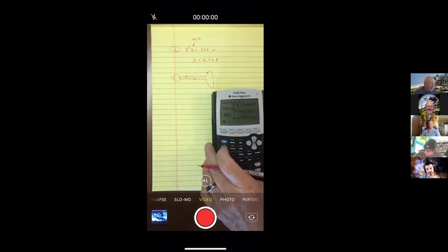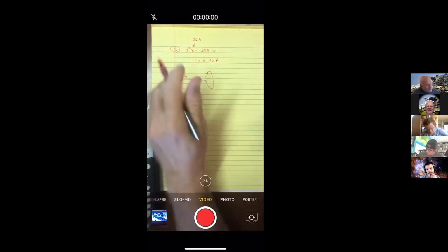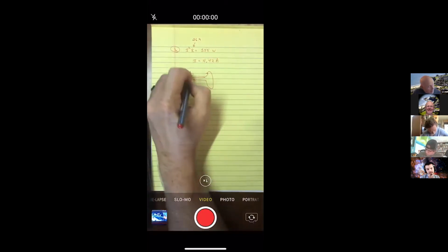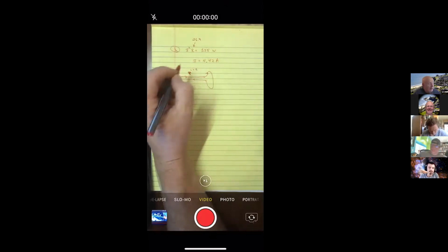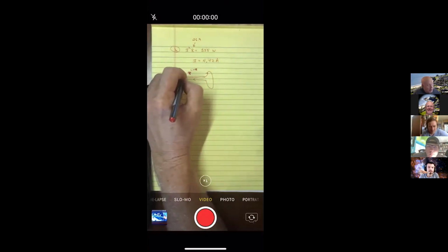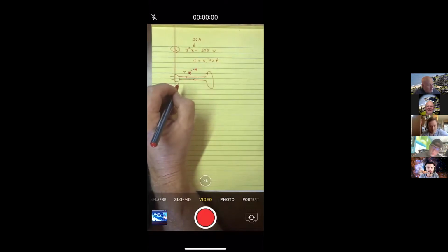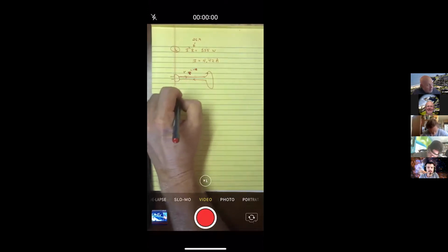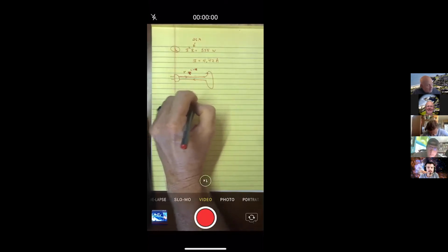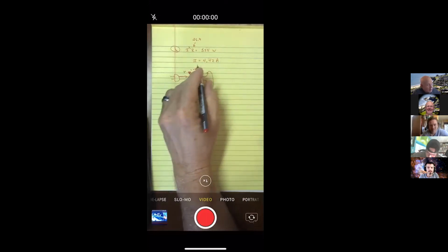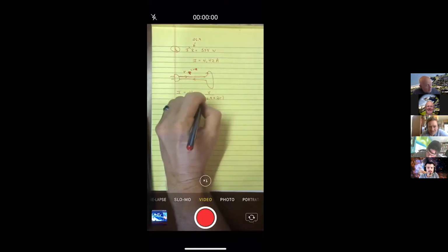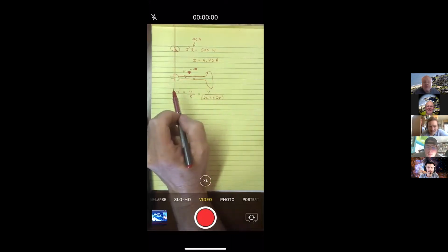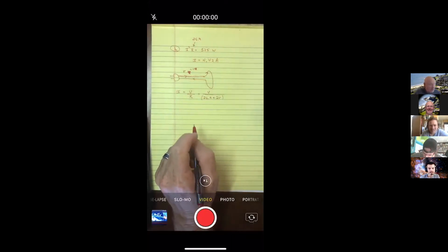And then, kind of like we did in A, but in reverse, if I said that this one wire right here had a resistance of, well, let me not use capital R, that might confuse you, because in part A, they said 0.9. Let me just call it little r for a moment. Because current is voltage divided by the total resistance. And the total resistance would be the resistance in the vacuum cleaner plus 2 little r's. Again, if you let r be the resistance of one wire in your extension cord.